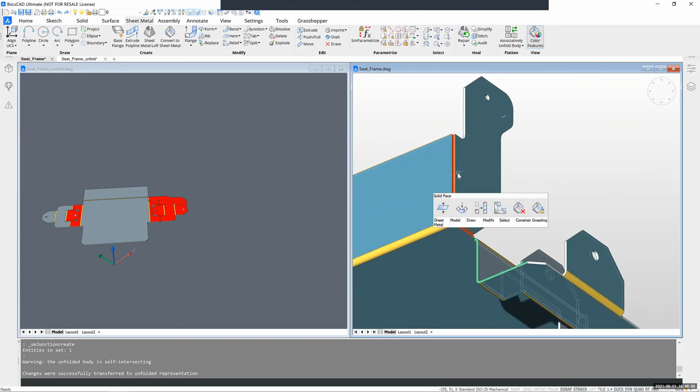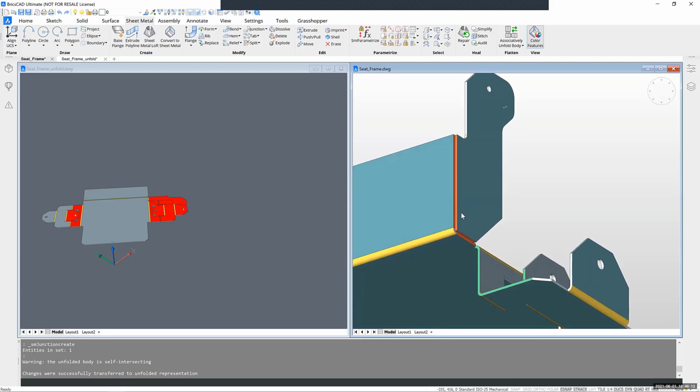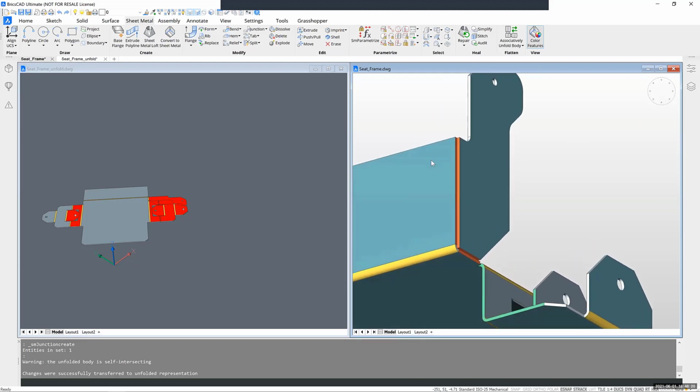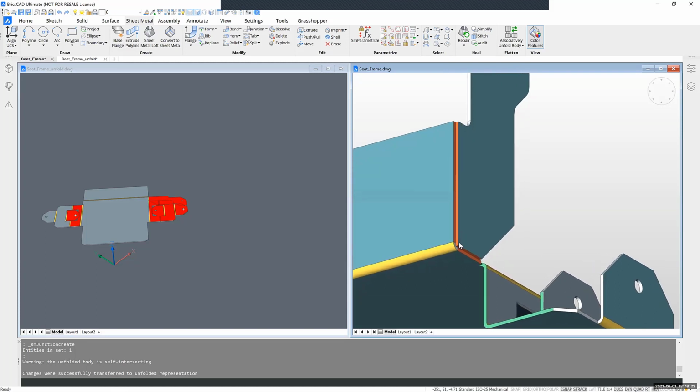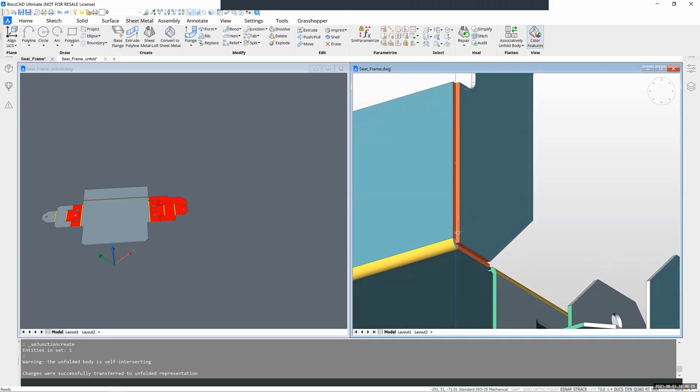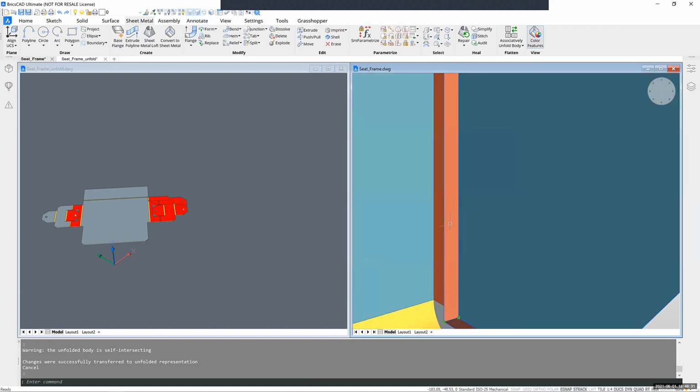So what I now need to do is create a new band. You don't see it appearing here either because it's just separate. It should be a separate unfolding, not of that main body. But if I attach it again with a band, it will reappear. So how do I do that? Similarly, you can select the face, only the face. Either your prioritization of faces is on and you can select it immediately, or you hold down Control if you're in solid selection mode, then you can access the face.